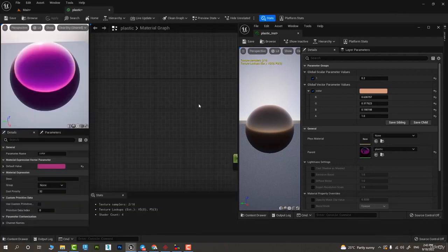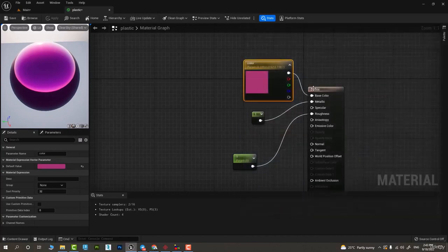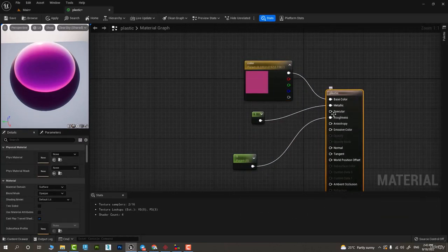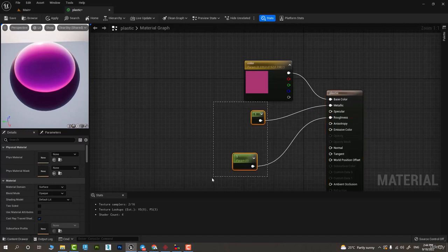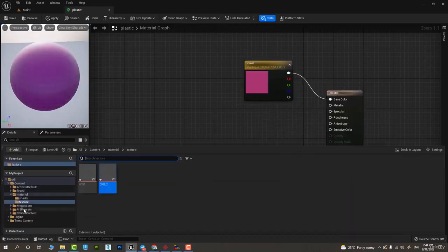And it's very easy. Now, if you wanted to use textures instead of color values, how would we go about doing it? Instead of these roughness, metallic, and base color values, how would we put black and white textures that could achieve the same effect for us? For example, if I put a black and white texture in my roughness, wherein the texture is black is going to be glossy and reflective, and wherein the texture is white is going to be opaque. Okay, I'm going to show you how that works.